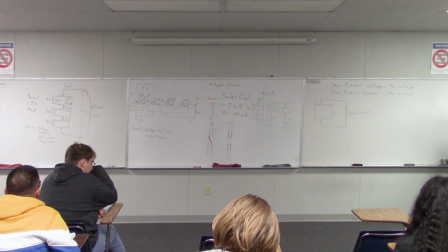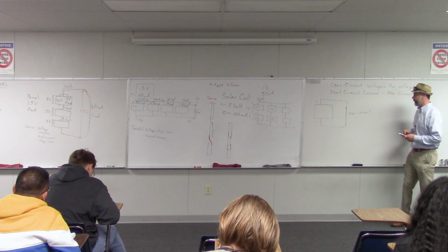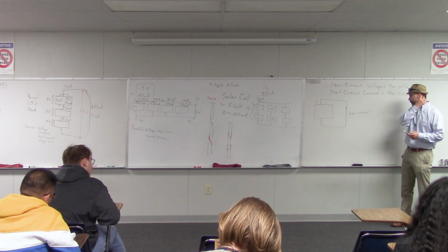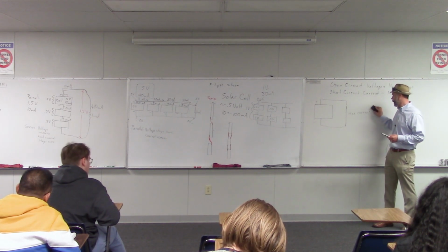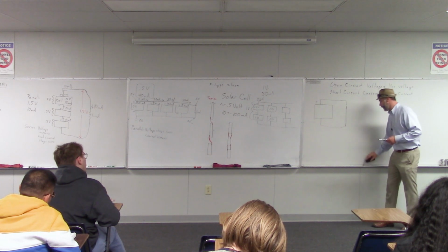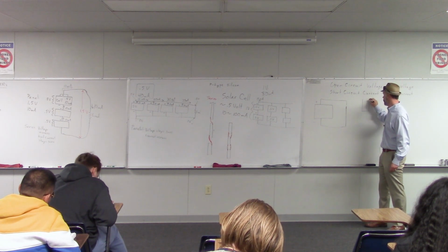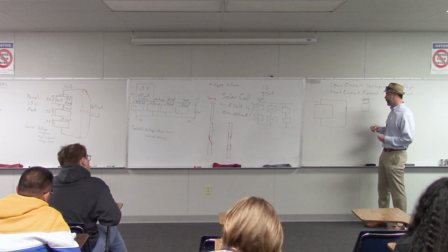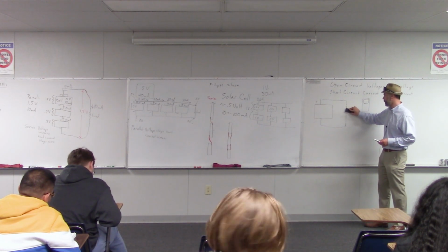Now, let's talk about how you would measure these, okay? So if you want to measure the maximum current, well, you're going to make a current measurement. So you're going to have your meter over here. And remember, a current measurement is a destructive measurement. So you have to partially deconstruct the circuit to make it.